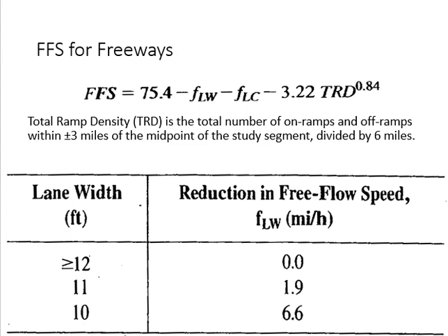The next one is lateral clearance. Lateral clearance starts from the edge of the last lane, the edge of the right-hand side lane. From here the lateral clearance starts up to any object which you have. So for example, they have two lanes. At the end of the lane, there is a yellow line, and then after 5 feet, there is a sidewalk.